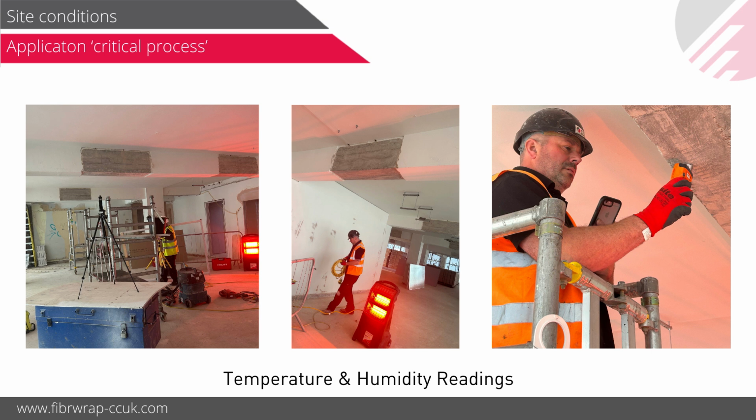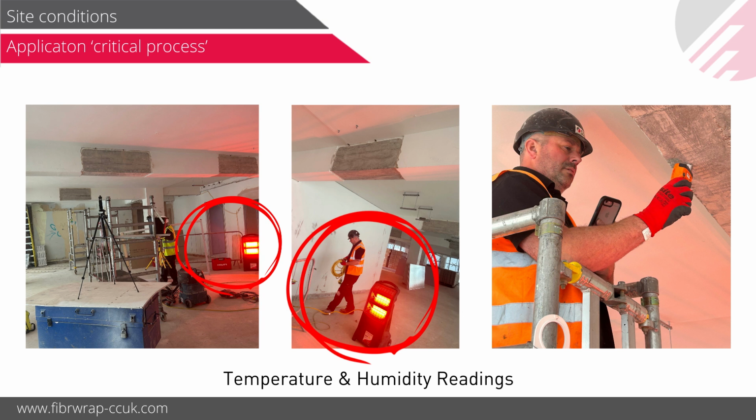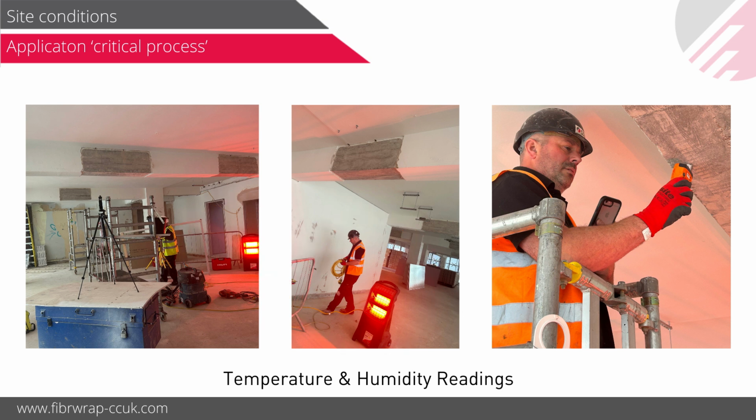But in winter months, it might not be possible to get that kind of temperature or climate. So they have to use these kind of artificial heating arrangements. They can enclose the area, heat the area, get that environment artificially, and then apply the FRP.